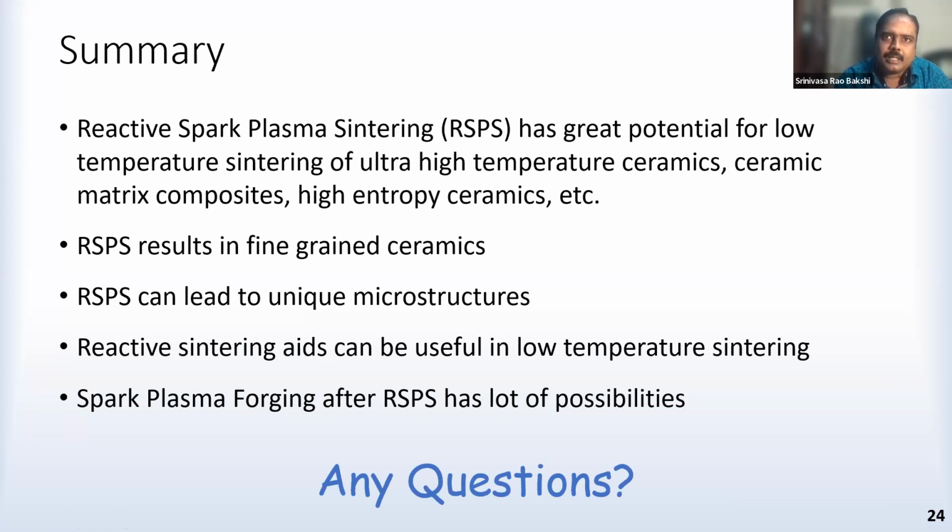And actually, for ZrB2, the surface energy is anisotropic, so we can see grains also elongated and so on. But for TiB2, it is not so. So even though it looks equiaxed, there could be crystallographic texture present.